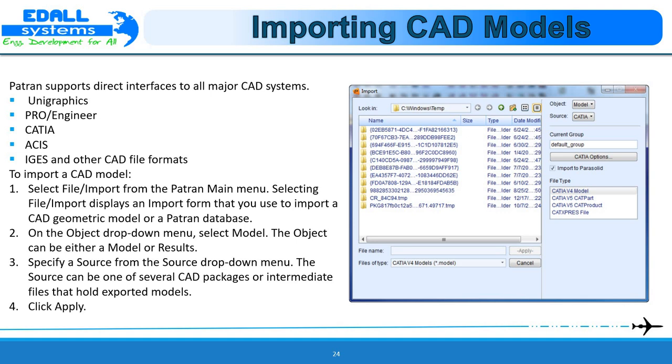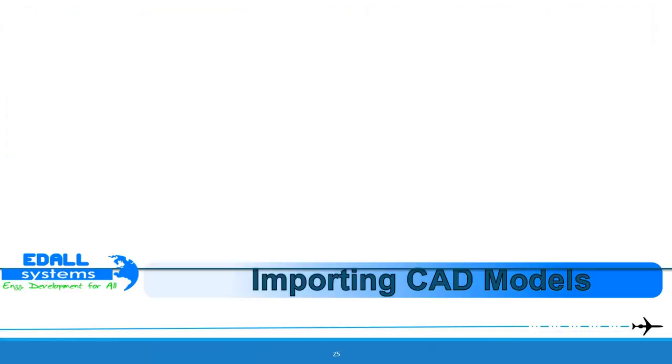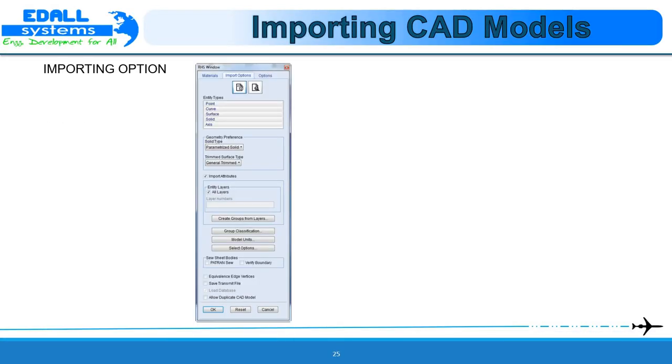Patran provides two types of CAD access, CAD import and CAD interface. CAD import allows import of a limited set of CAD geometry types like IGES, STEP, PROE.GEO, CAD Express, and Express Neutral files through Patran's built-in legacy translator. CAD interface supports a wider range of geometry types and is a more modern implementation that improves geometry via a Parasolid translation process. This is the default method for most CAD import types.